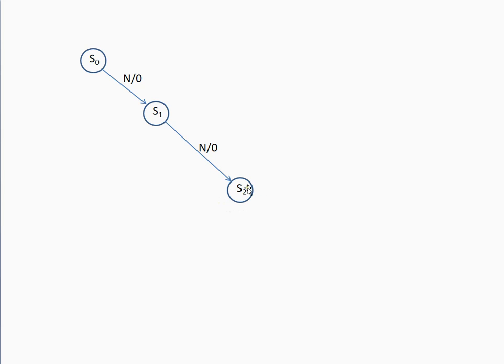So in this case, by being in state S2, the system practically encodes the fact that it has received 2 nickels. This continues on like that, going to another state and another state until we have the 20 cents. So at this point we have received 1, 2, 3, 4 nickels, so we have 20 cents.